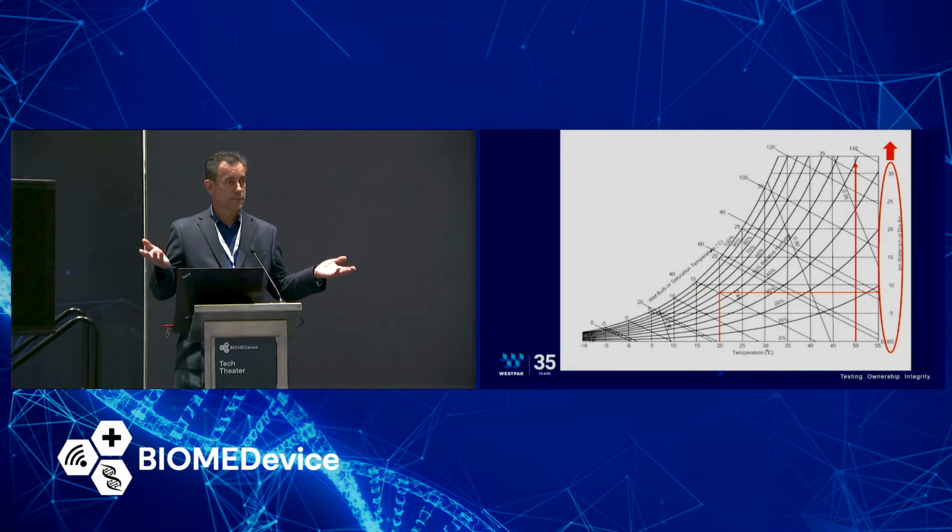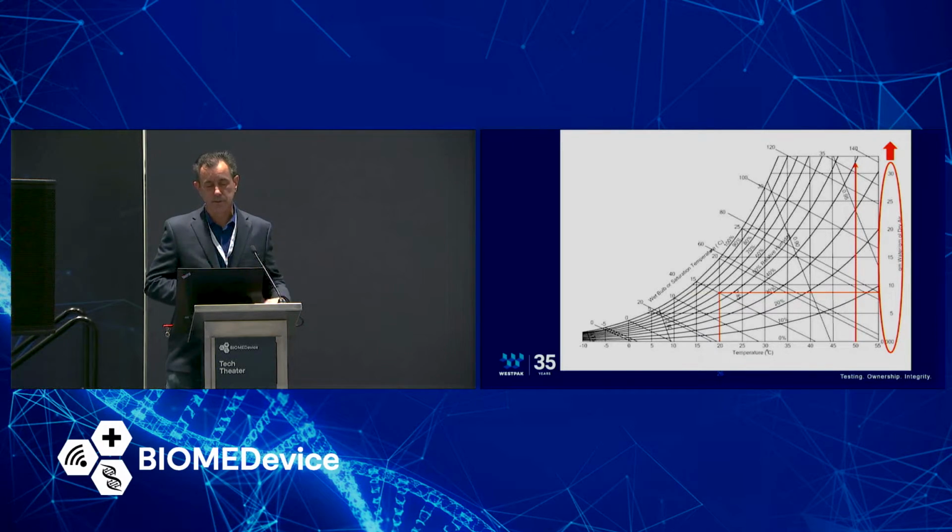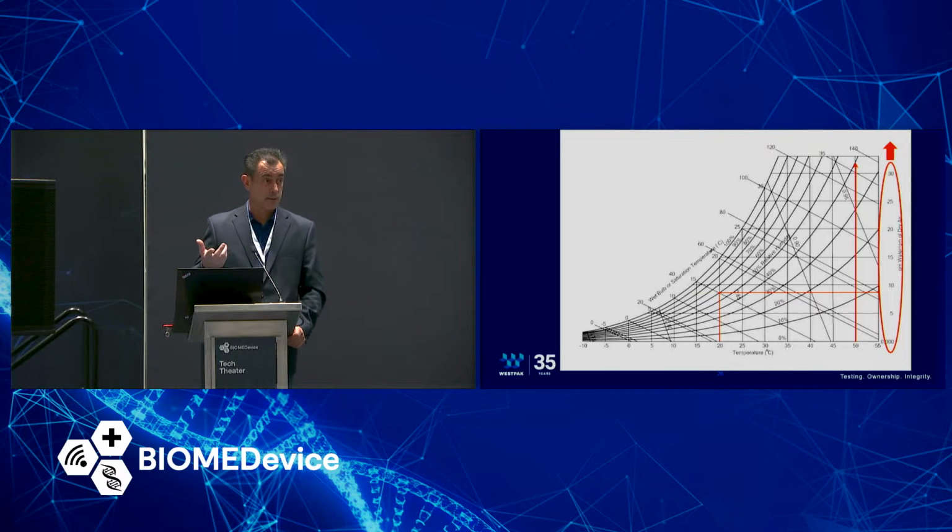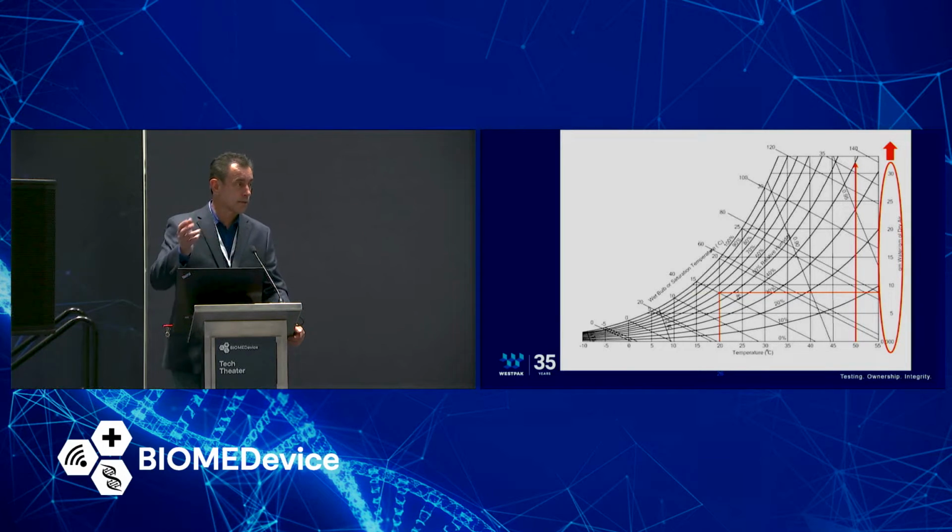Now, is that necessarily bad? What we've experienced early on when we were doing accelerated aging, we used to put in very high humidities, about 75% humidity. And what you would notice is that the poly material, because it was laminated together with a water-based adhesive, would separate. And you'd have these laminate separations of the material. And this was concerning because now you have to write an NCR and you've got to dig around and do analysis on it and all that.